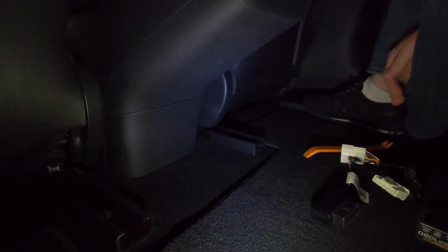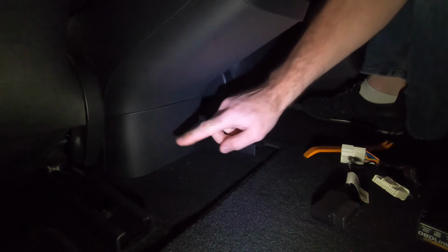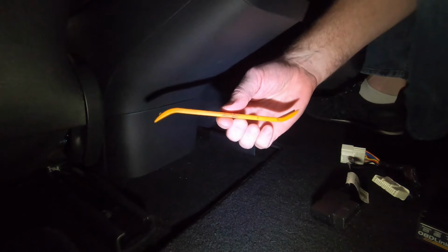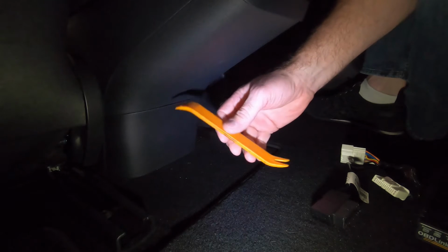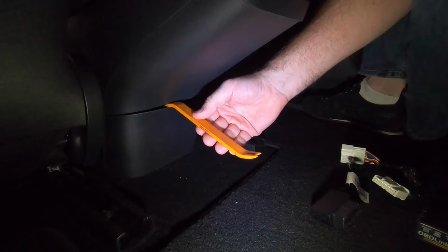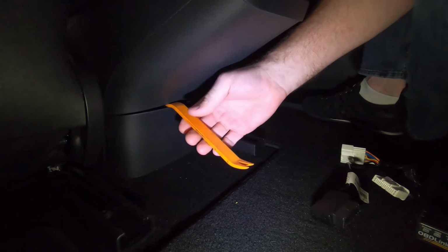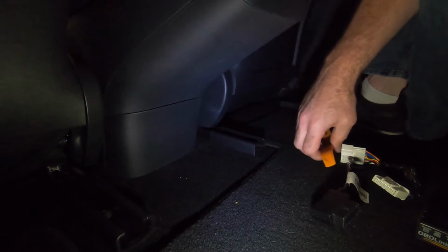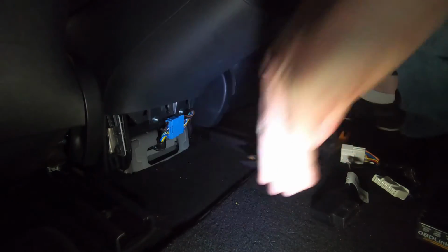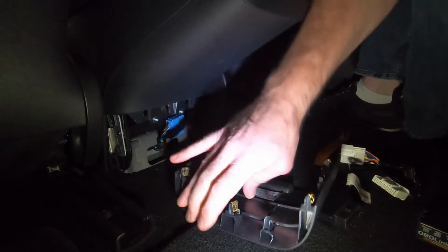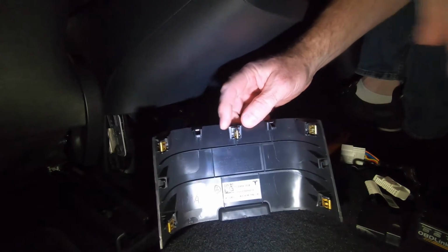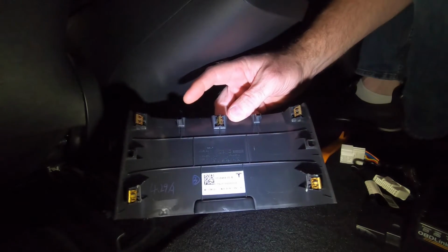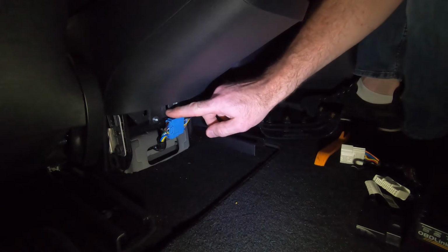So while we're waiting for the car to power down, we're going to remove this panel here. You can do it with this nice plastic tool, it's not going to damage anything. Push it in here, pull up, and start undoing the clips to that cover, or you can just do it by hand with no tools. Put one hand either side of the cover towards the bottom, squeeze really tight, and then unclip the cover. So it comes off that easy. When you go to put it back in, remember this clip goes to the top, and you can see that lines up with the slot there.